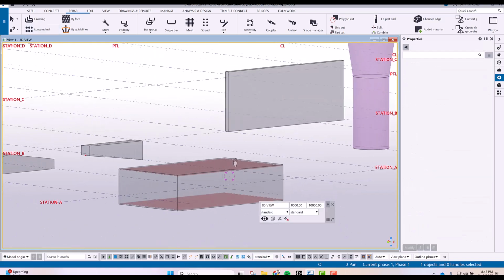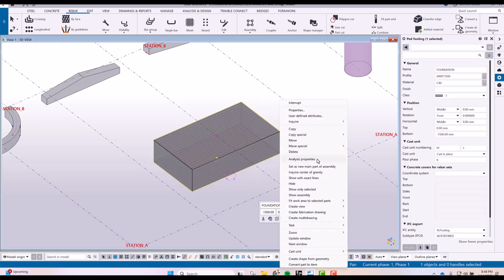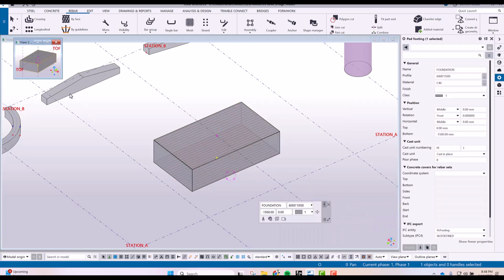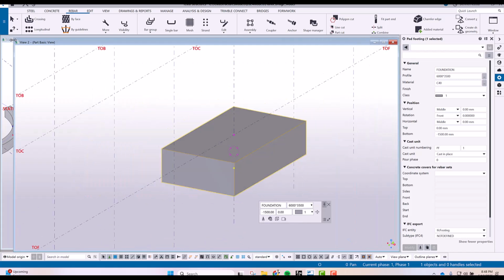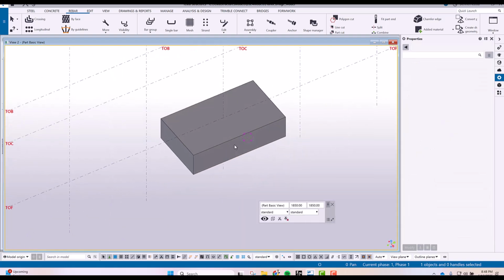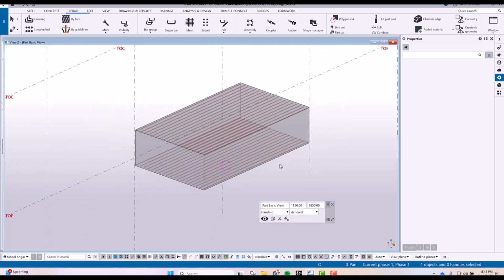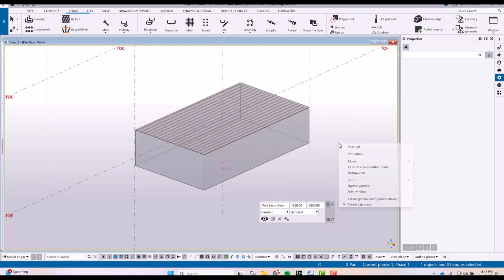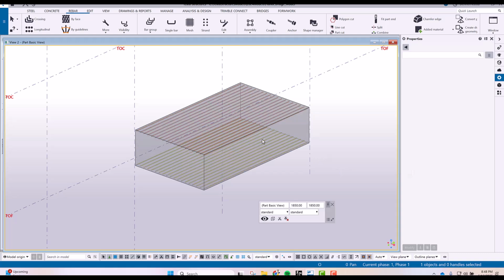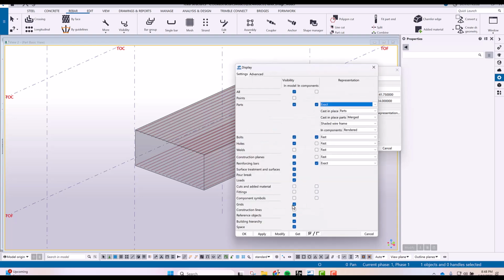Okay, so once we have this longitudinal bar, what I will do here is maybe isolate this view, so that we can concentrate only on this particular element. All right, so Control 2, you can see the transparency of the concrete, and with this one maybe I'll just show only selected. Okay, I think that's redraw. And then here maybe I'll just turn off the grid line.